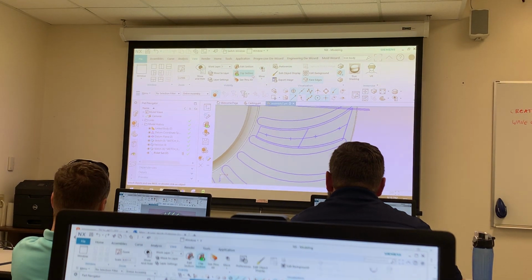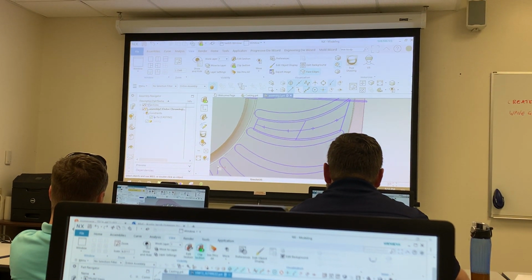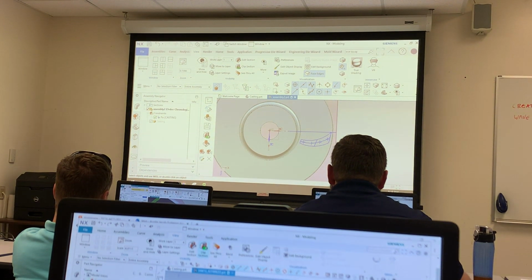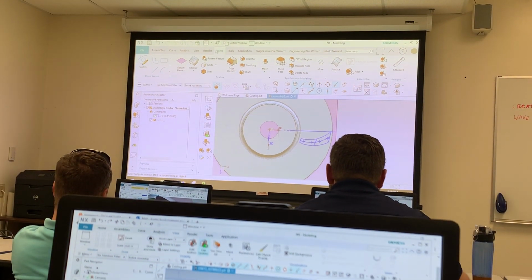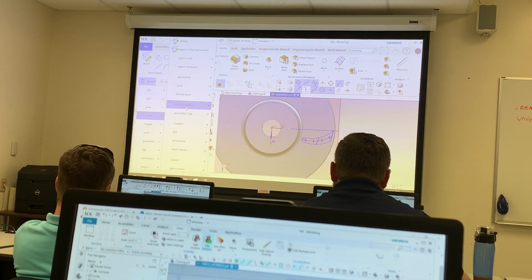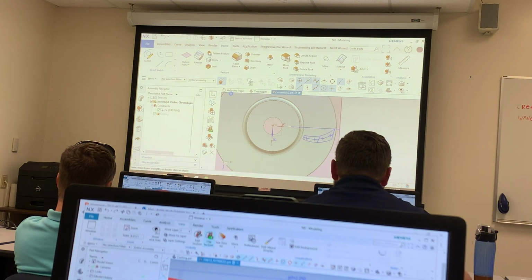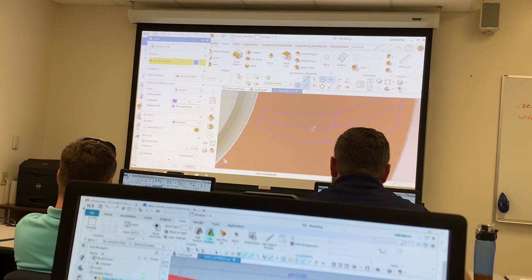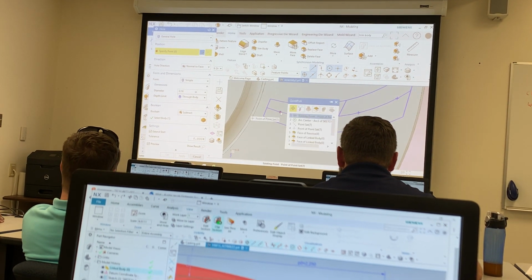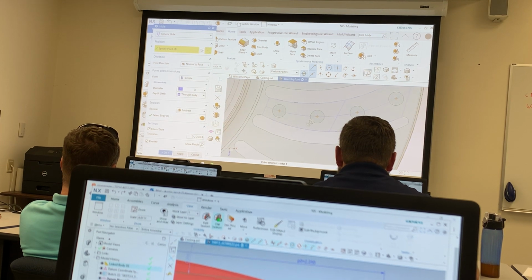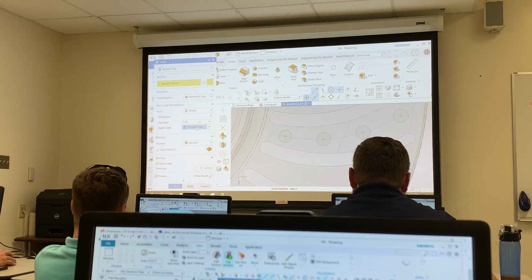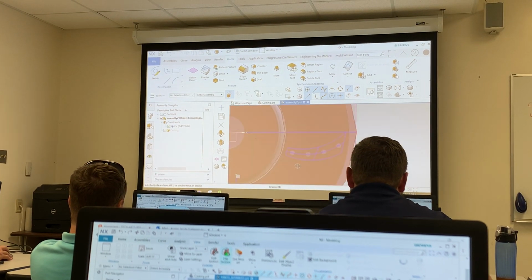All right, I can turn off that section view, turn those sections on. Now you know how to do this. I'm going to put in a hole. Insert design feature, manually a hole. And instead of just picking point by point, I can actually stop and pick the whole point set at one time. 0.18, and they go all the way through the body. And when you get that, you're done.